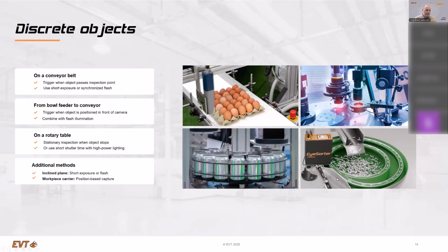The same is true here for a system at the end of a ball feeder, for example. First of all, detect if it's the right part in the right orientation. That was always really difficult. What is the right setup? In this case, because the parts are on a belt, you can use a line scan camera and get a very high resolution. First of all, the AI can recognize what part in what orientation. That's what AI can do very easily.